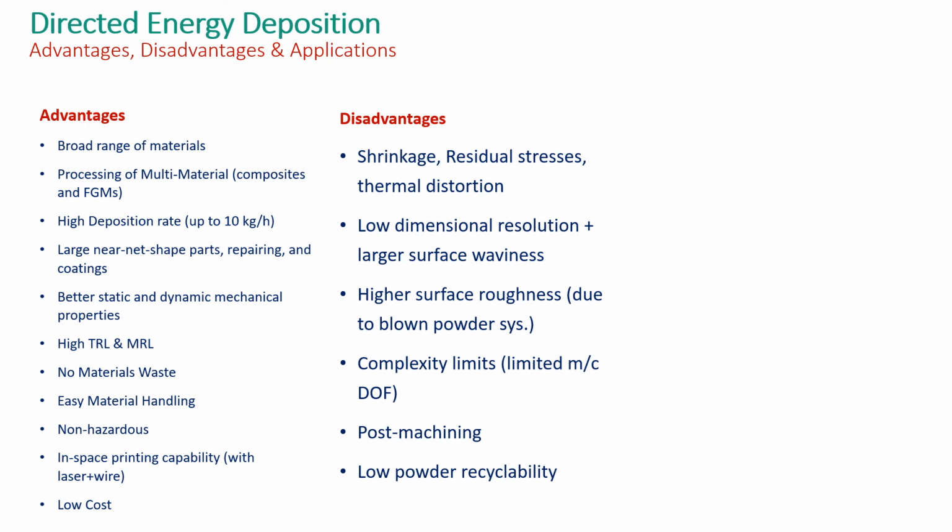And along with that, we obtain higher surface waviness or surface roughness in this technique. And the complexity limit: because we are feeding the material in from one particular direction, and the laser head is also moving in X and Y direction, only X, Y, and Z direction movement is possible. So it limits the complexity we are expecting.